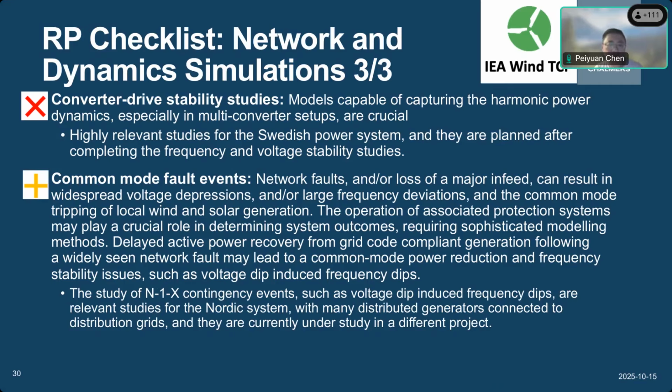So it is extremely important for us to look at the protection of these small generators in the low voltage grid, so that a fault deep in the transmission system does not cause cascaded tripping of these small generators at a larger scale over a larger geographical area, which will in turn impact the system frequency.